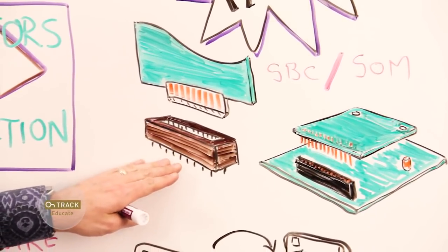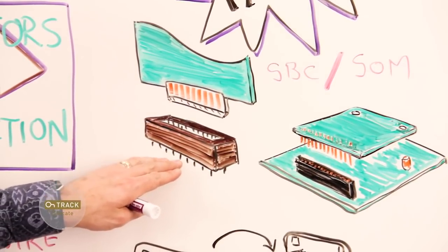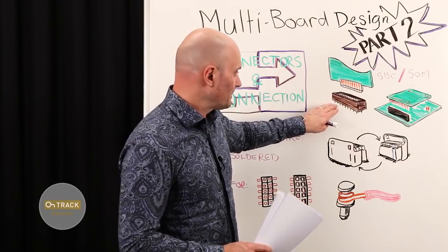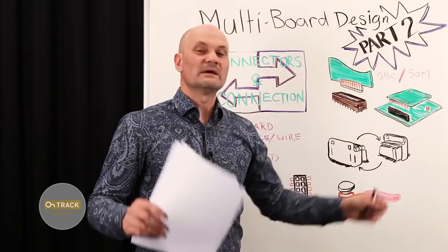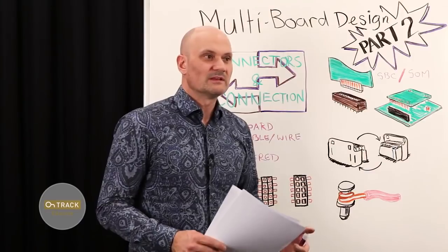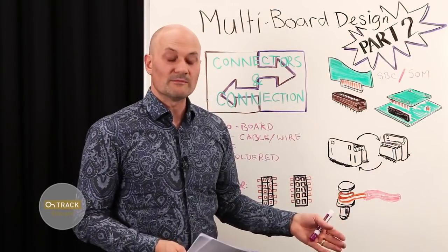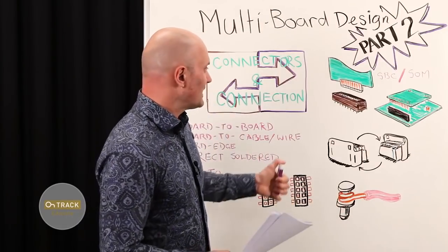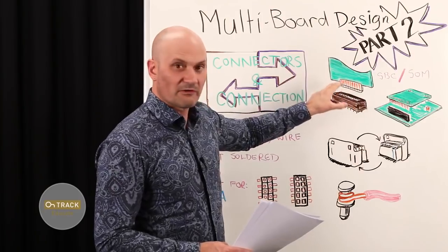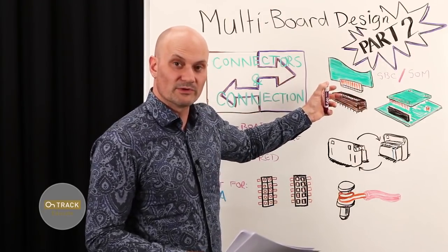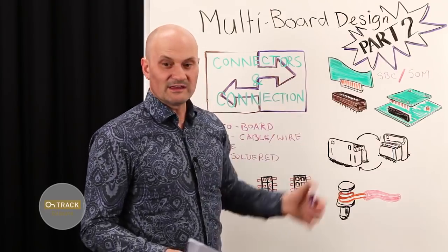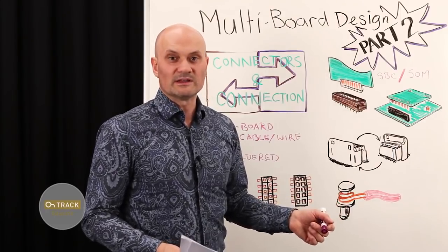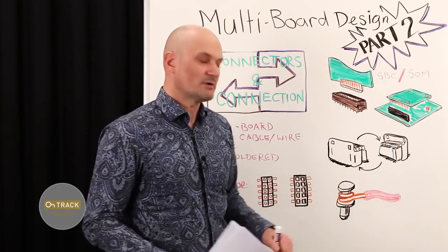It has an advantage of being fairly high density, and these are usually specified for industry standards like PCI, PCIe, Q7, and there's many other standards that are basically designed for computer motherboards and their peripherals, or high-speed digital assemblies, and they may define good grounding and differential pair signaling, so you get fairly good throughput. So for example, PCIe connectors with the right designed card edge, you can usually reliably get 5.8 or more gigabits per second on each pair.